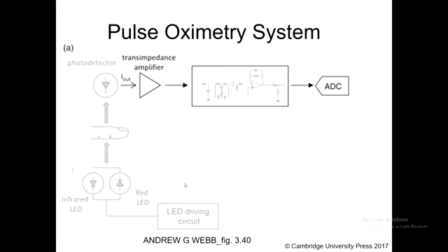Okay, so we've got a signal train here where the LEDs are arbitrated in their switching by some smart arrangement that's hooked up to typically a microcontroller that decides when to switch these 2, and it knows when it switched them, so it can compare as it gets signals through from this analog to digital converter. So all the way through here, there's a continuously variable in magnitude signal going into an analog to digital converter to digitise it in a form that can be then read in by a computer.